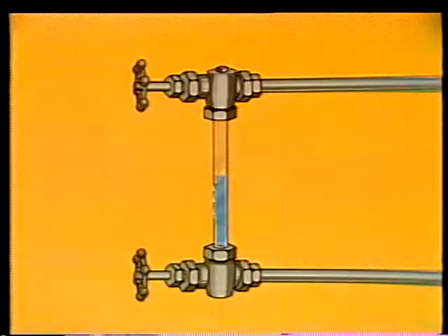Glass erosion occurs for the same reason as any other kind of erosion. A fluid flowing over a material will gradually wear it away. In a gauge glass, the glass is more susceptible to this kind of damage than the metal parts. Glass damage is corrected by replacing the glass.